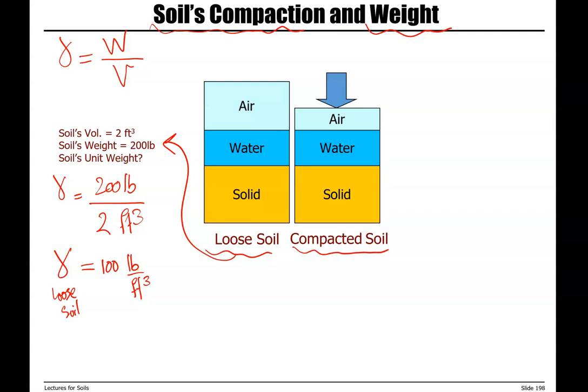Now, when we compact our soil, we want to see what happens to volume and weight. Weight of soil sample, if you remember, air doesn't have weight. Weight of air is 0. So when air is removed, there is no change in total weight.